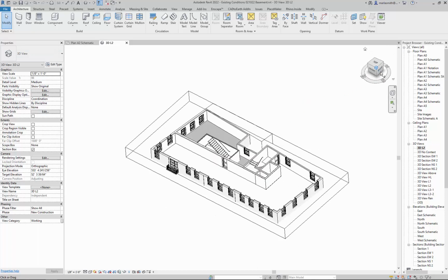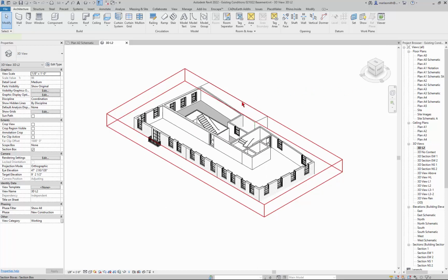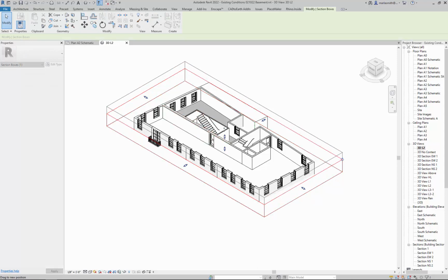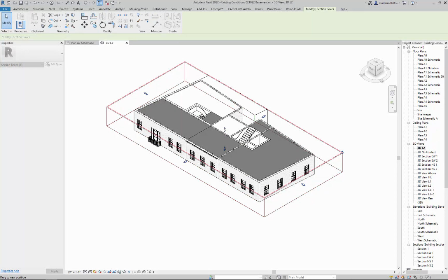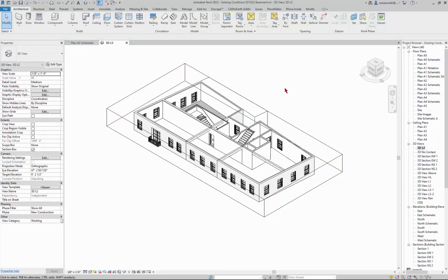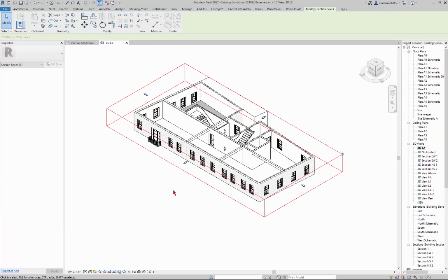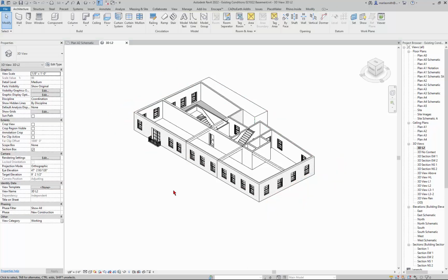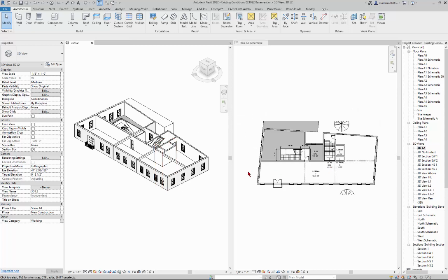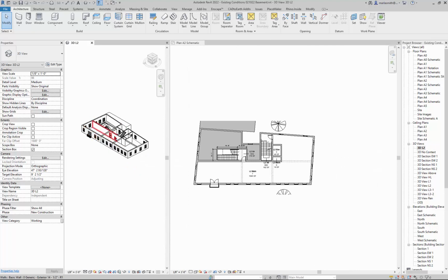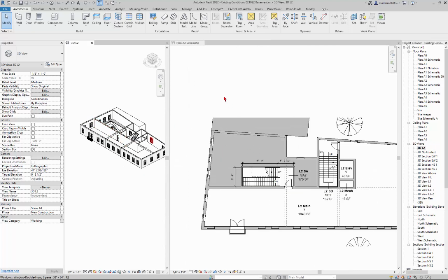and it'll pop right into that view. And if I go to my 3D view, you can start to see it, and then I can kind of pull it up. It's kind of in the door right now, but just get it to where it's right below the floor, maybe like that, where I can see what I'm working on. And if you want to, you can hide the section box, just to make it a little cleaner. And then I'll go to WTZA and maybe pull this one over a little smaller so you can still see it, but I get a little bit more room for this.